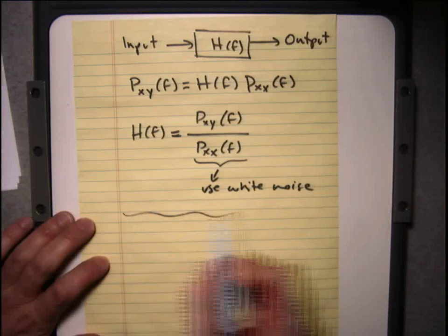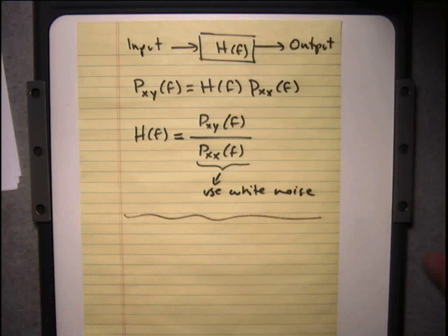Okay, so this is some review of concepts on random processes. This is pretty much the same as just pinging the system with a delta and just taking h of n from the output. No, it is not the same thing as pinging the system with a delta, because the delta here is not the signal. The delta here is the autocorrelation function of the signal.